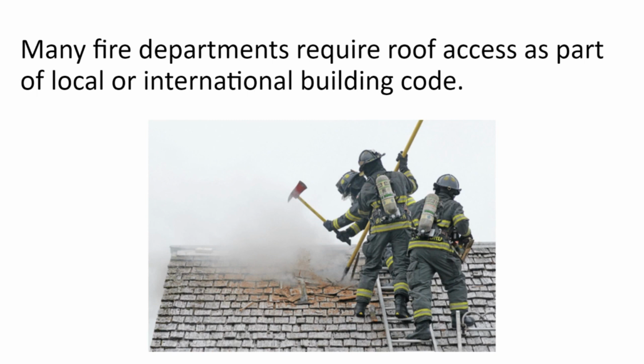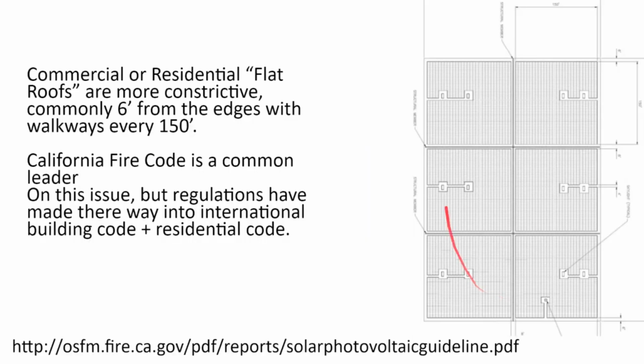Flat roofs, such as commercial rooftops, have their own rules and regulations, which are commonly staying 6 foot from the edge of the roof. That is simply a good practice to discourage maintenance workers from getting too close to the edge of a building, although it can make solar on top of tall, skinny buildings a little bit more difficult to locate.